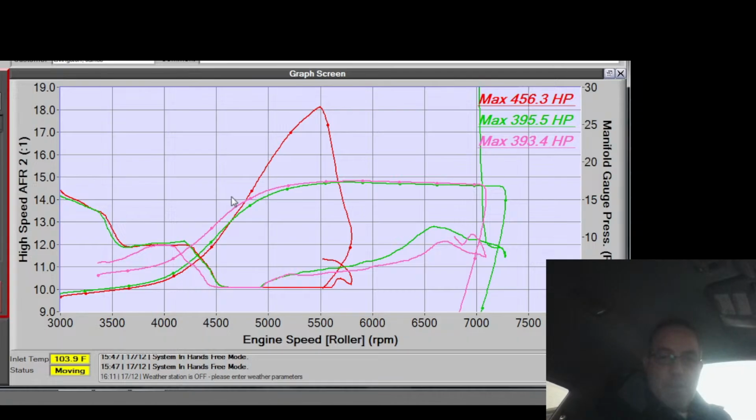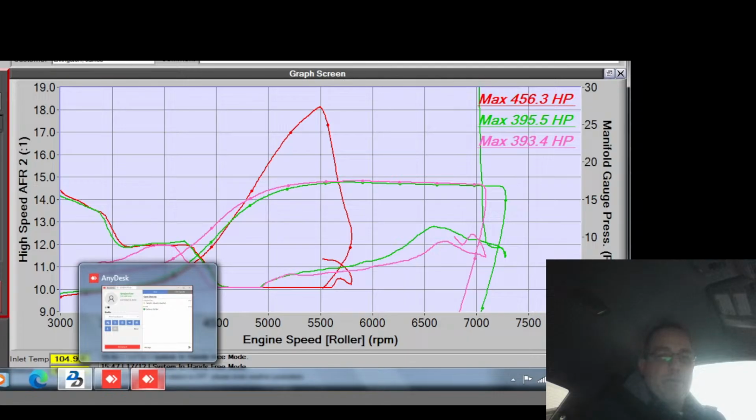All right, I think I've got this thing traveling enough. I'm going to do a couple tip ins and see how angry it gets. My trims right now are 0, which is great. Oh, that was good. Okay, I like that. So at 2,000 RPM, if I tip in, I'm not getting any hesitations. That was a full throttle one, no hesitation. All right, I dig that.